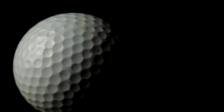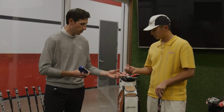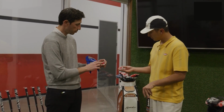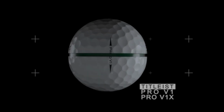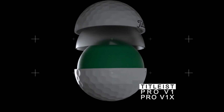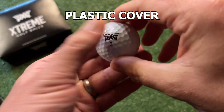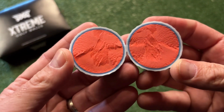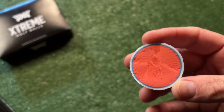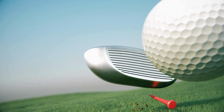Modern golf balls are constructed in 2 or 3 parts. 2-piece balls, made of rubber and plastic, are favored by casual golfers for their durability and account for 70% of all golf ball production. In contrast, 3-piece balls, used primarily by professional golfers, consist of a plastic cover, rubber thread windings, and a core that may contain gel, liquid, often sugar and water, or be solid. The dimple pattern on the ball's surface enhances its flight performance.